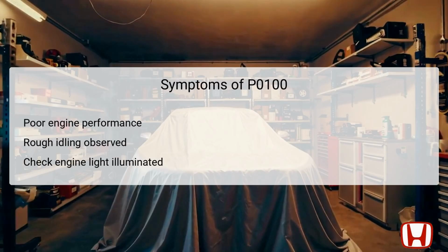Vehicles experiencing DTC P0100 may exhibit a variety of symptoms. Poor engine performance can be at the forefront, as improper air-fuel mixture affects acceleration and efficiency. Drivers may also notice rough idling, where the engine does not run smoothly, potentially leading to stalling.